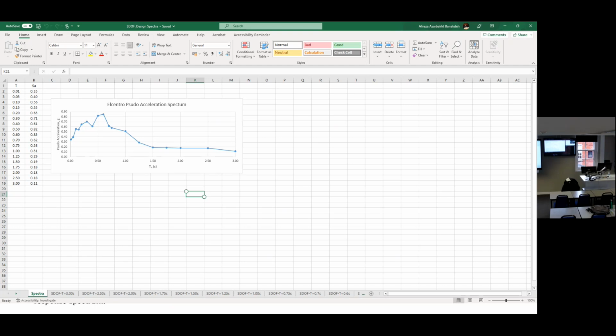So changing your structural properties, especially stiffness, will influence your external forces as well. It is not the case with wind loads. The wind load depends on the geometry of your structure, how wide and how tall it is when the wind blows, and how much of an obstacle you make in front of the wind, so you get some forces. But in the case of earthquakes, seismic load in Eurocode 8, it's totally different.